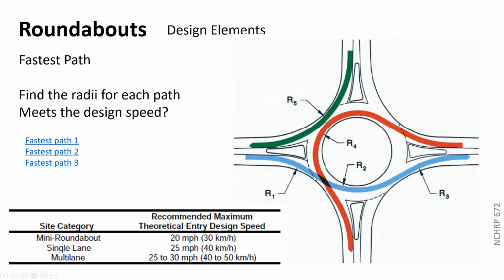Right, and there's an inflection point, and there's another radius, an inflection point, and then another radius through here. Each of those R1, R2, R3, they're probably not the same, almost never are. We often draw a spline curve through here and match that up really nice and smooth to try to approximate what we think the vehicle's path would be. And then we'll snap in and figure out what the radii are in that. And then we'll check those radii